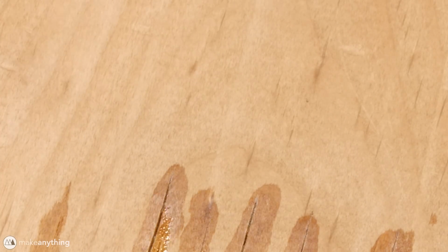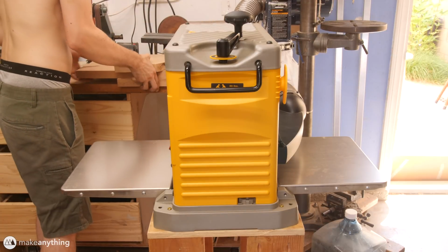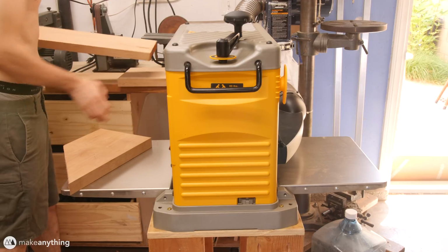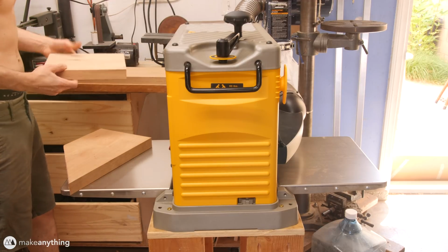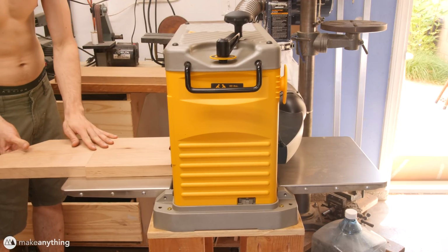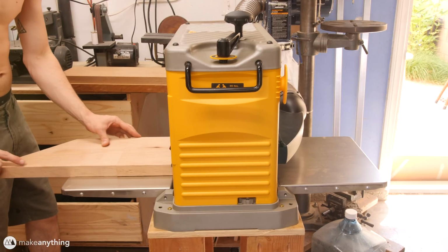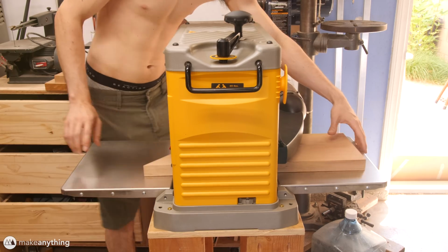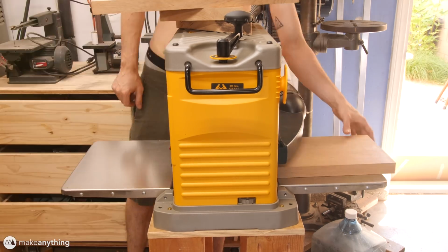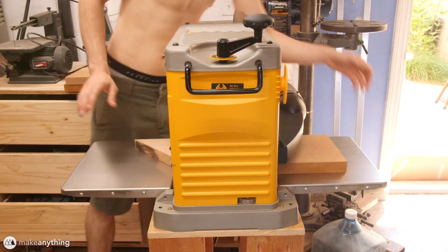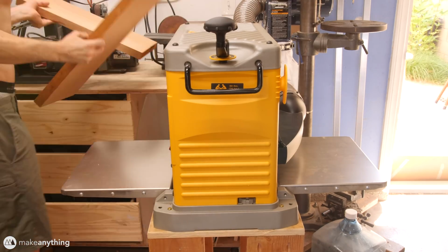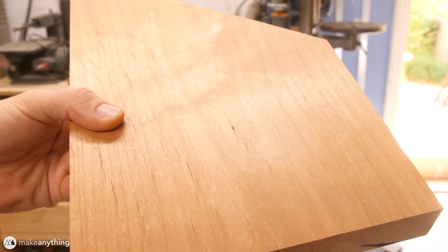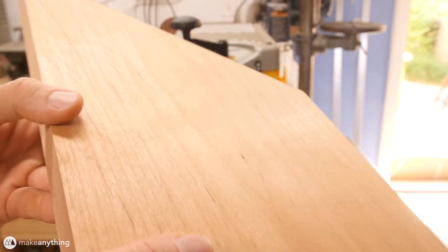So I did have to fill all of those up with super glue. But once that was dried, I went ahead and took everything to the planer and started shaving them down. This planer isn't meant to handle pieces shorter than 12 inches, but by stacking them together like this, I was able to safely feed them through. I went ahead and fed all the pieces of wood through over and over again until they were all nice and completely flat. And I just put a new blade on this planer, so it's a really clean, smooth surface.